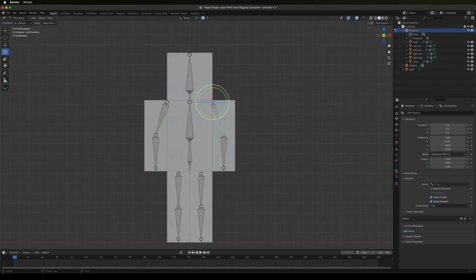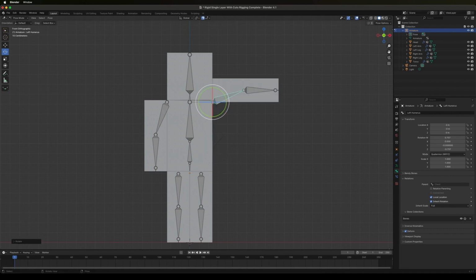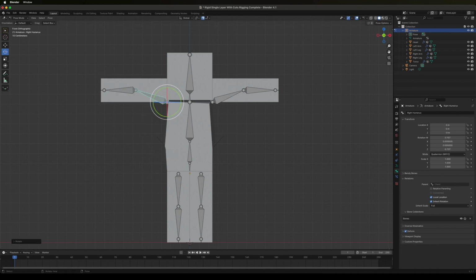We select the armature and go into pose mode to do this, and the easiest way is to select the top of the upper arm bones and R, 90 or 270, enter, to rotate them into the correct position. We note that the torso deforms slightly when this happens, and this is something we will fix with weight painting later on. Personally, I find this pose a little difficult to work with, at least for the Minecraft character, and normally work with the arms down, only putting the character into the T-pose when exporting. We export the model to VRM while in this pose, and we'll see if it's had the desired effect.